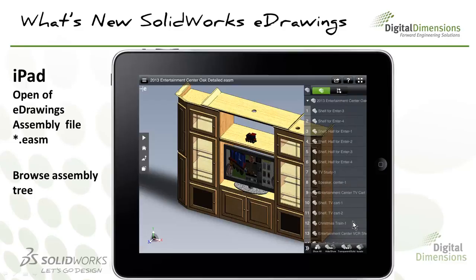Keep in mind, you could select on a component and isolate it or hide it, and if you wanted to change the view, you can come over here to your view icon and access your standard views. And then if my current configuration had an explode, I could toggle the exploded state, or I could return home or play animations of standard views.